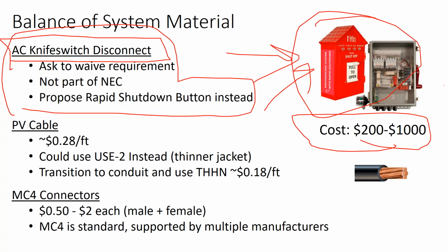Can we use that instead of a solar knife switch disconnect, and make the point that the solar array is already landing on an accessible disconnect right inside the building, and it would be confusing to the fire department to have a knife switch disconnect outside the building for the solar array that doesn't de-energize the emergency backup system. I think that could become kind of a mess down the road, with good intentions.